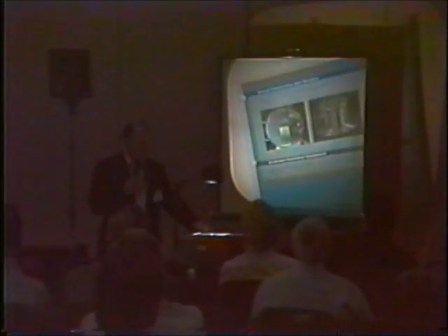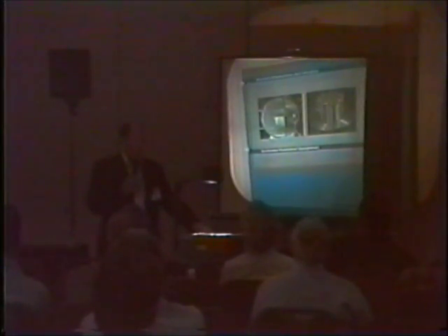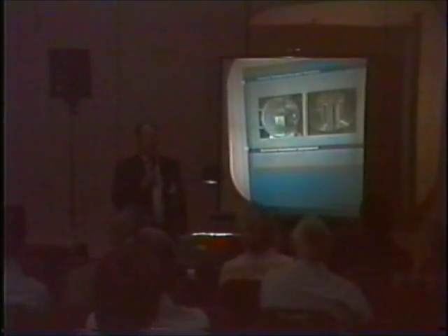Okay, we're going to see a Marx generator, what it actually looks like. That thing in the center there that's round, that's got the device sitting inside it. This is a Marx generator. This is a large metal tube that has a cap that goes on the end of it, and you fill it with oil, very much like the oil that's in your automobile.